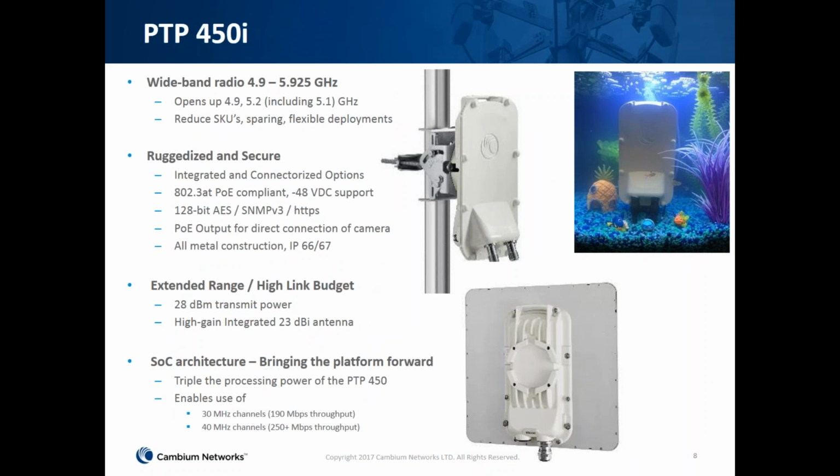Hey Bruce, as far as the PTP 450 in the 5 gig band, looks like we have a question on when we're going to be opening the channels to 40 megahertz. So that's a good question. We just recently introduced the 30 megahertz channel on the 450 and also what I'm showing here on the screen, which is our PTP 450i. We are going to be releasing a 15.1 software release. I expect that to be going into beta in the next week or so and being available in probably, I would say, 3 to 4 weeks out, being able to operate in 40 megahertz channels.